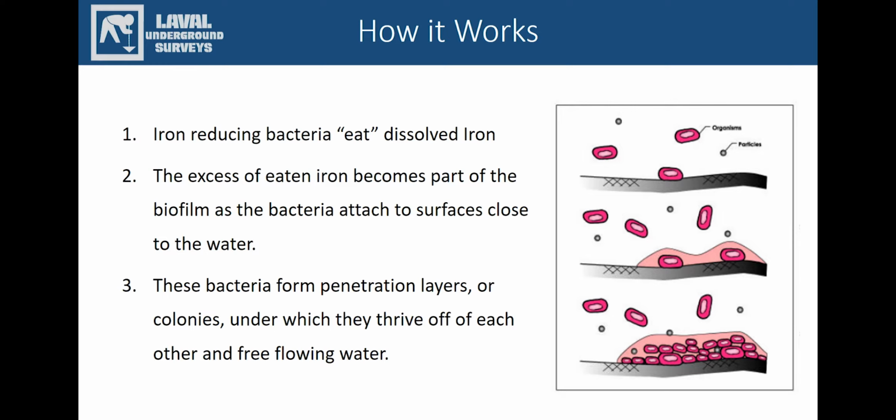We find that it's important to talk about how bacterial biofouling actually works and how it becomes one surface. When oxygen in the air mixes with dissolved iron particles in the water, the iron changes to white, then yellow, and finally to red-brown solid particles that can settle out of the water. At a critical point, the bacteria sense that there are significant numbers of them, and it would be more advantageous to act as a group as opposed to acting individually. At this point, the bacteria turn off the planktonic, or unattached, portion of their genetic material and turn on the sessile, or attached, portion of their genetic code.